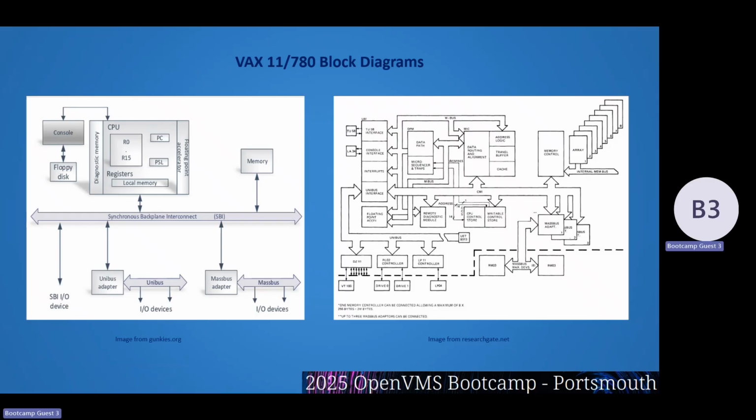One of the really neat gizmos that you could put into a 780, actually any PDP or Unibus system, was something called an LPA11K, Laboratory Peripherals Accelerator System. That board had a sub-processor on it. It had digital to analog and analog to digital converters on it, so you could talk to the outside world. It had watchdog timers on it.